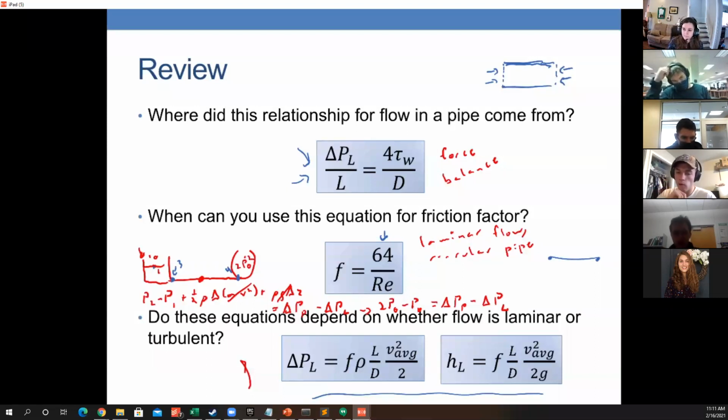And how does this equation take into account that the force due to the shear stress on the wall is different depending on how close to the wall you are? Where is that reflected in this relationship? Well, it's at the wall is where that force comes from. Shear stress acts all the way through the fluid, with the fluid sort of pulling on itself, but it is most significant at the wall, and that is where the significant friction arises from.